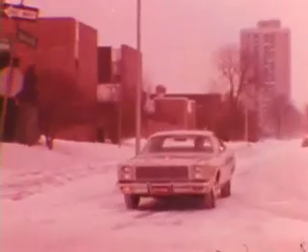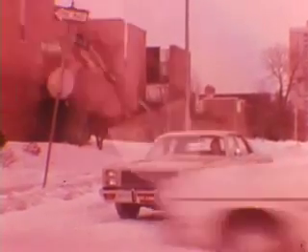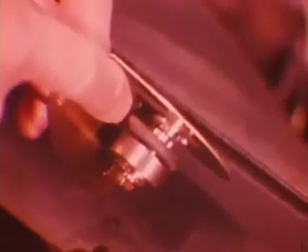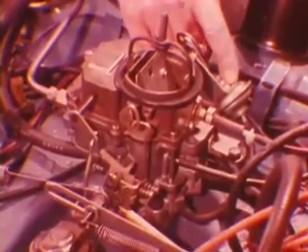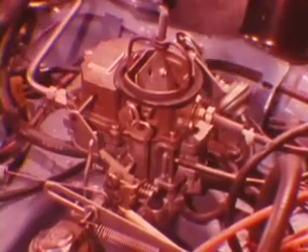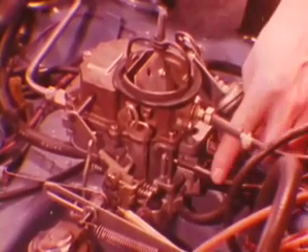And that brings us to the second drivability operating condition, engine partly warm. Some engines stall at idle speed as you back out of a driveway or stop at a nearby crossing. Here we can begin by making sure the assist heater does not cause the choke to open too soon. The vacuum kick diaphragm must open the choke properly. Fast idle speed and cam position must be correct. Idle enrichment should be operating, and there must be no vacuum leaks.